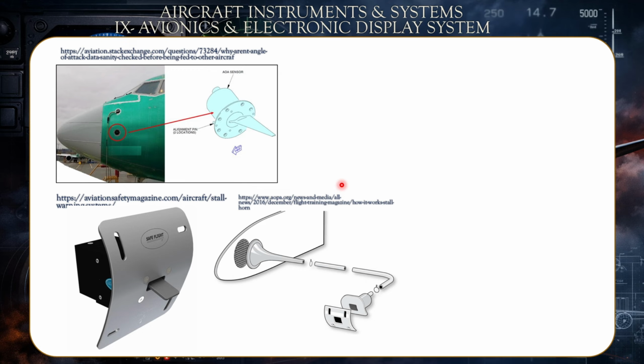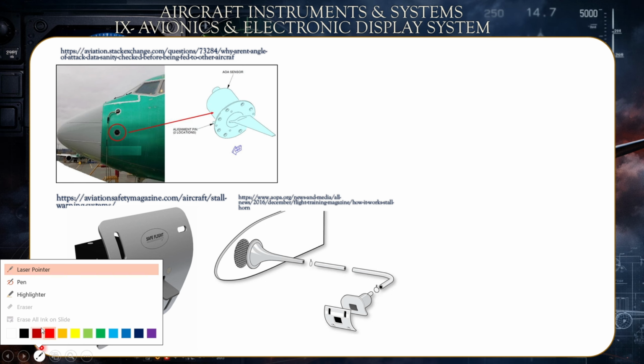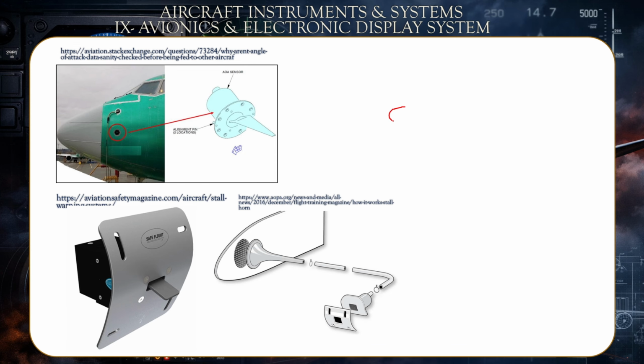And this is again how it measures the angle of attack, by measuring and comparing the shifts in the capacitance value. Because if you remember, the value of capacitance is given by epsilon times A divided by D, where A is the area of the armature that is housing the electric field, one of the armatures, not both of them.